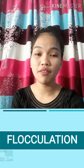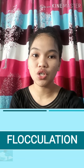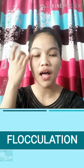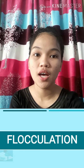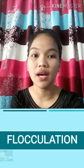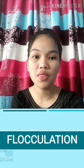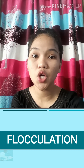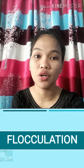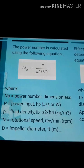Vertical shaft turbine flocculator. In new water treatment plants and those that use direct filtration, vertical shaft turbine flocculators are typically used. This type of flocculator has an impeller attached to a vertical shaft that is rotated by an electrical motor. So, important design parameters for this type of flocculator include power number, effective tank diameter, and the ratio of impeller diameter to effective tank diameter. The power number is calculated using the following equation.